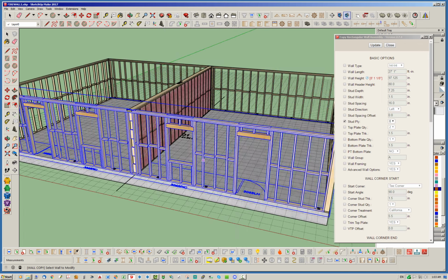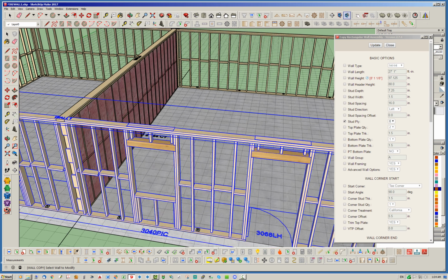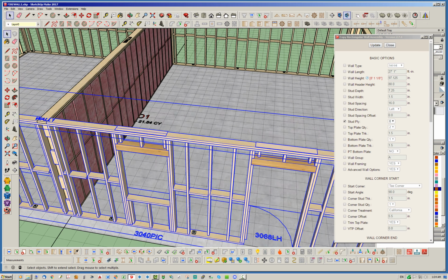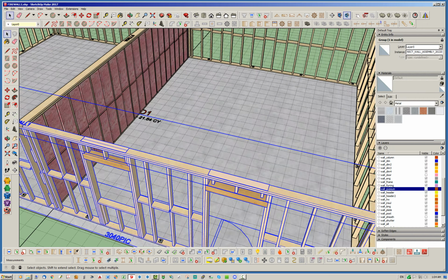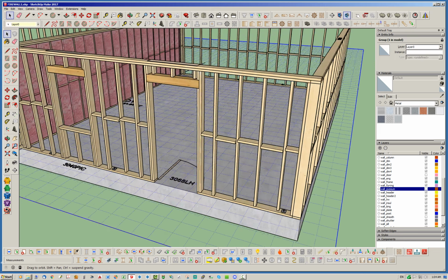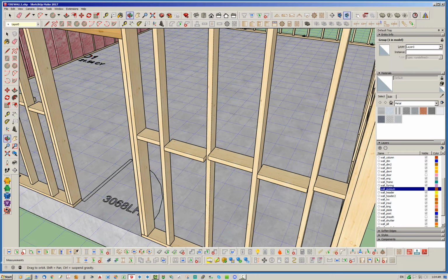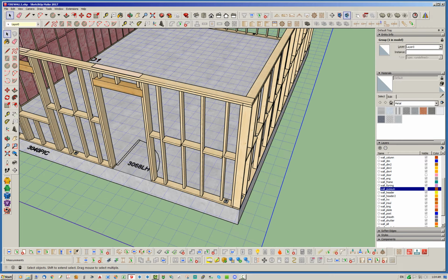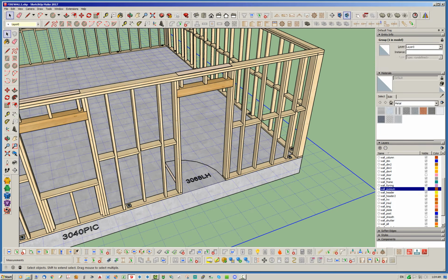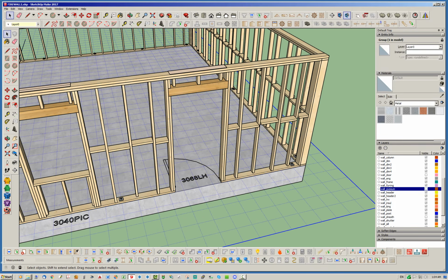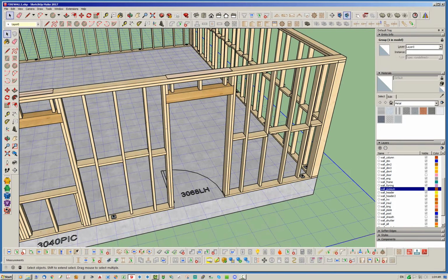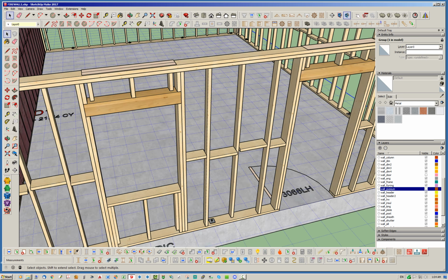Okay, and now let's take a look at this front wall. This is where it gets a little bit more interesting. So let's just close that out. And now the blocking gets a little interesting with staggered studs, but I guess it is what it is. So yeah, you can see that the common studs that get generated, as well as the cripples, all are staggered. Of course, the trimmers and king studs for the openings remain the same.